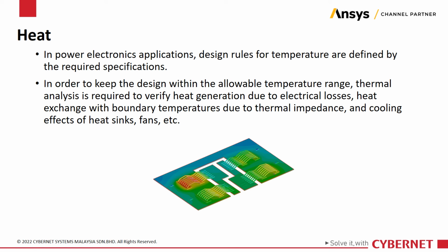Finally, we will show an example of thermal analysis. In power electronics applications, design rules for temperature are usually defined by the required specification. To keep the design within the ideal temperature range, thermal analysis is required to verify heat generation due to electrical losses, heat exchange with bounded temperatures due to thermal impedance, and cooling effects of heat sinks, fans, etc.